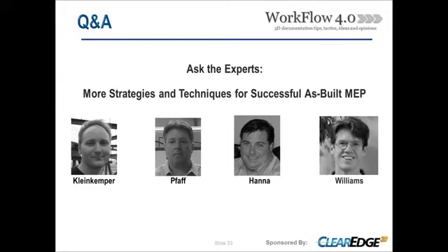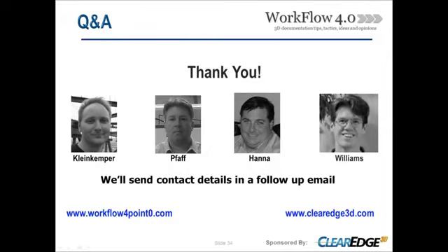So what we chose to do was, using our total station, we went in and located common features on the building, and then we moved the point cloud to that same coordinate system as the model. This way, all the registrations and all the point clouds came in exactly where they were supposed to. So we basically geo-referenced to the client's existing model, and that worked out really well.